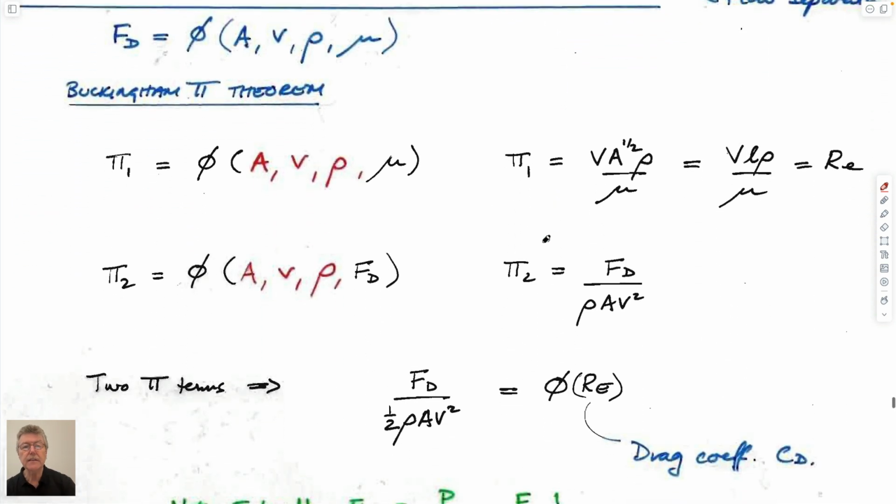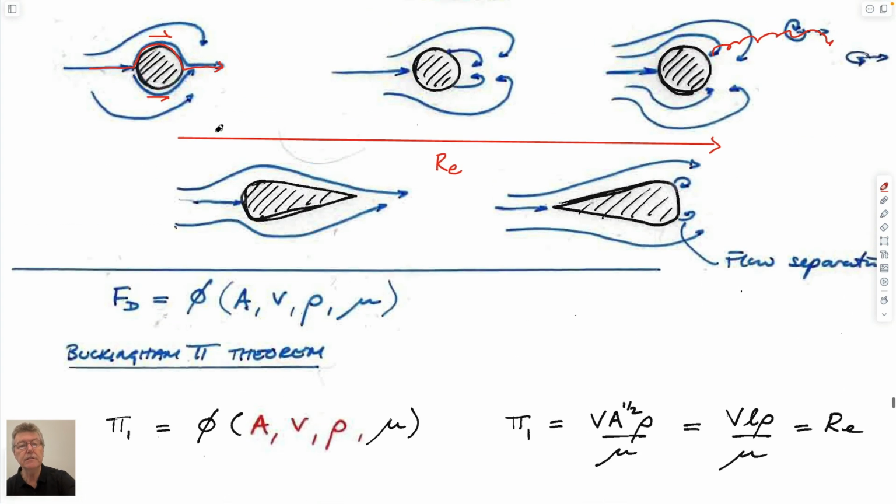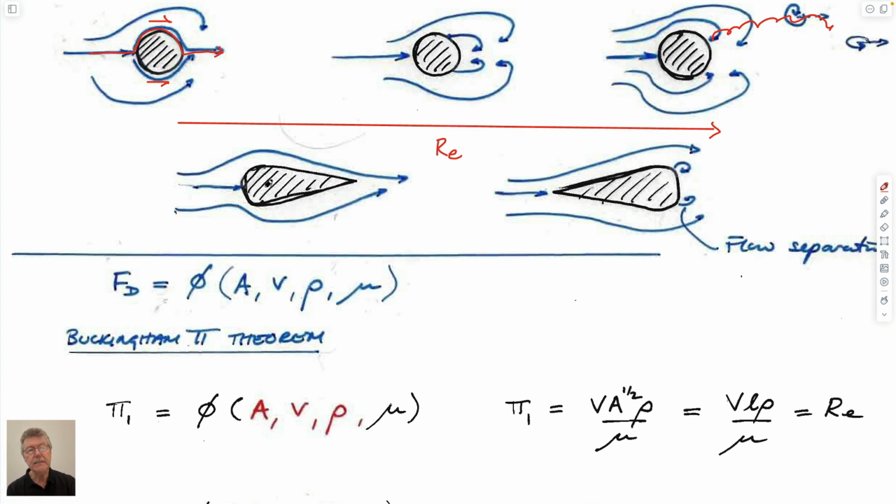We can also go back, I guess, to dimensional analysis and think about this. If we imagine these systems, we're going to classify them in terms of a force that we want to apply. And this force is going to be equal to the drag force, which I'll call Fd. So if we want to be a cyclist pushing with force F, we're resisting this drag force. And we could get this drag force from what we did with these closed form solutions, because we know what the net force is that's applied on this structure, or we could measure it in the wind tunnel.